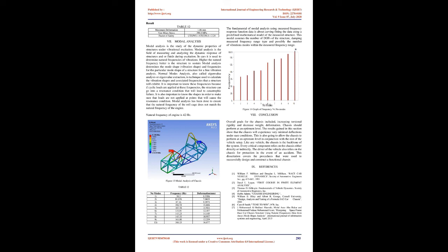The fundamental of modal analysis using measured frequency response function data is about curve fitting the data using a predefined mathematical model of the measured structure. This model assumes the number of DOFs of the structure, damping, measured frequency range type and possibly the number of vibration modes within the measured frequency range.